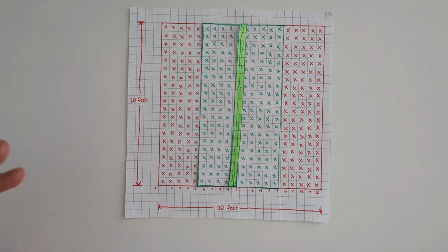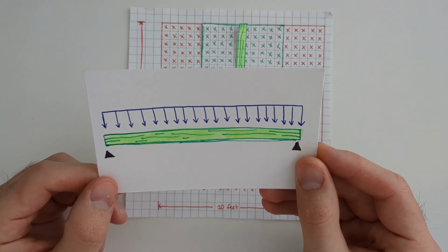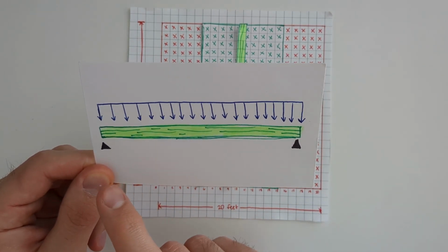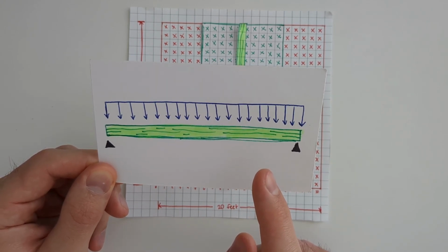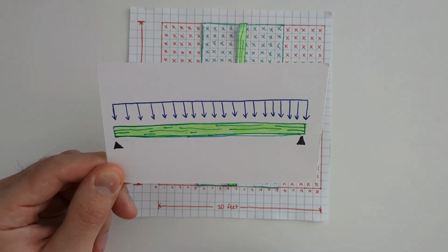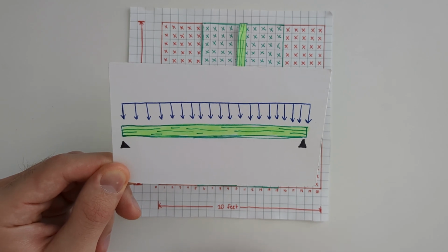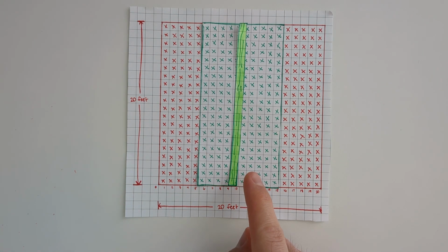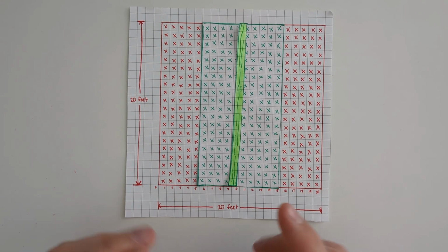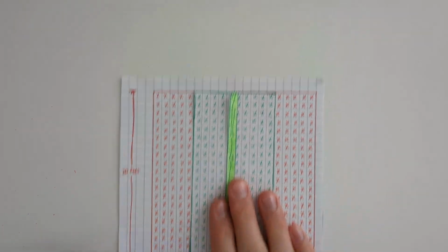Okay, so how do we use this to determine the size of the beam? Well, in structural engineering, we design our beams using a 2D analysis. We model the length of our beam and apply a linear load on it to determine what kind of reactions the beam is going to have. So we need a way to convert this tributary area into a linear load. Let's see how. Let's look at our pressures from a different perspective.